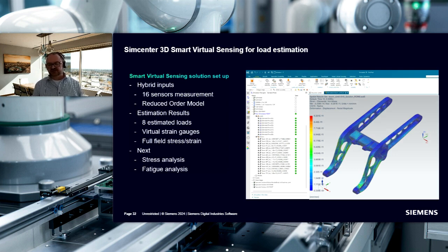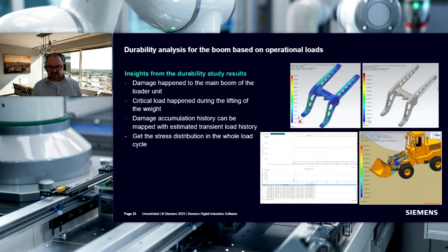and then back calculated the load again and got more or less the same distribution of damage and the same lifetime predicted by these operational loads, given by the few measurements. Knowing now that if you put our measurements at those points in a real structure, we can use these measurements directly to back calculate the loads. And that's what we did on that.